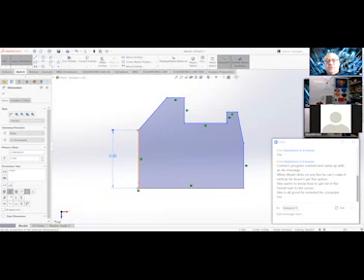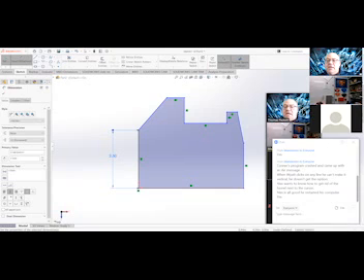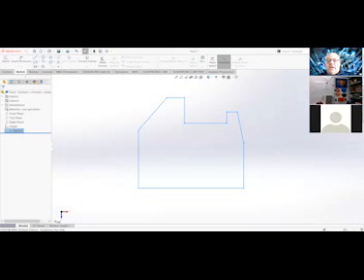And if you're done with your sketching, there's a green check mark here, and there should be a big green one over here in the top right. So if I hit the green check mark, that means I'm done. If I hit this mark here, it means I'm done. And I'm good. Now that closed my sketch. So I'm going to show you this. If you close out your sketch,